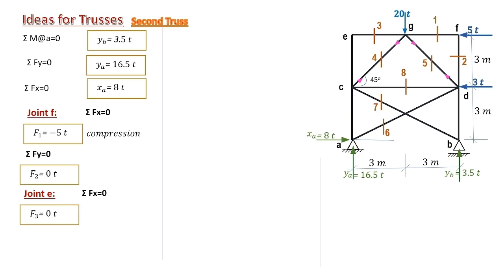Note that not all members are marked. We are just enriching our imagination, and therefore we will attack only the marked members. To go to members 4 and 5, we need two equations in two unknowns. Please note that 4 and 5 are forming the K shape but inverted. So we need two equations.